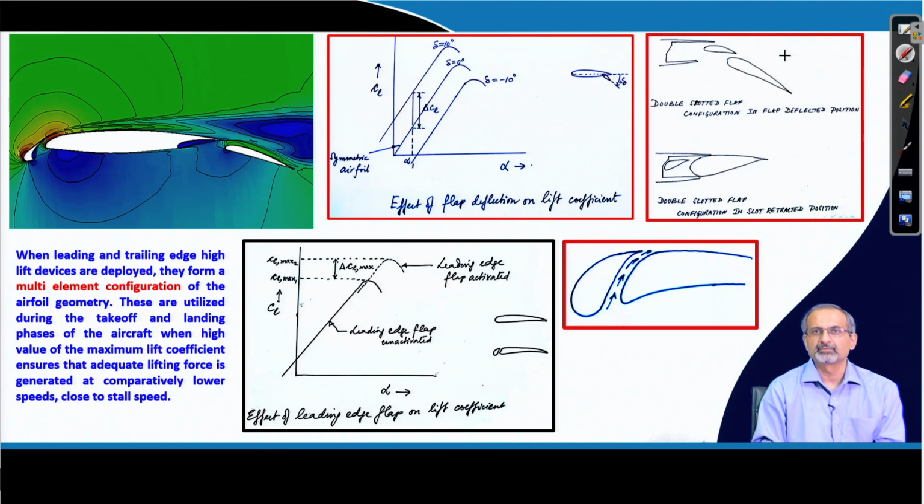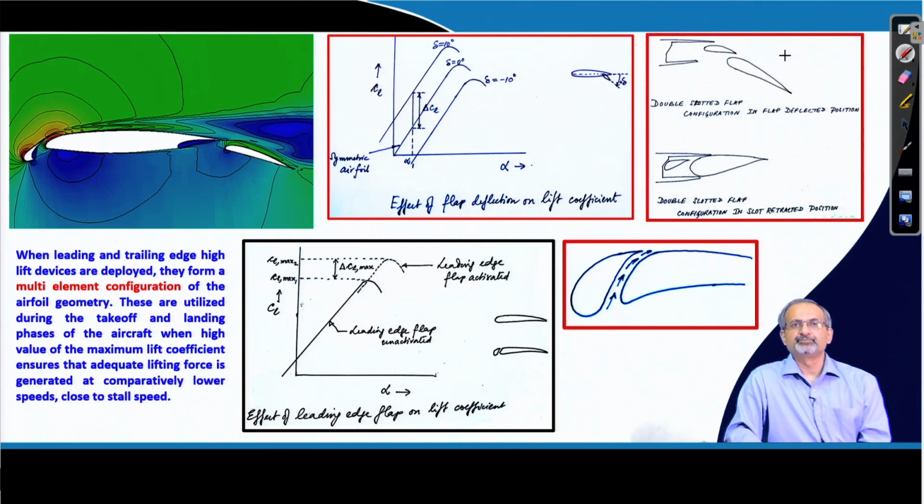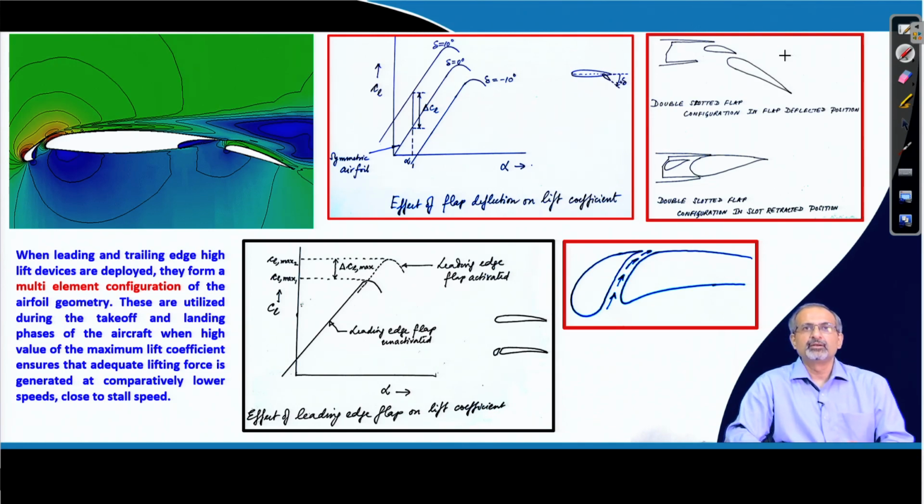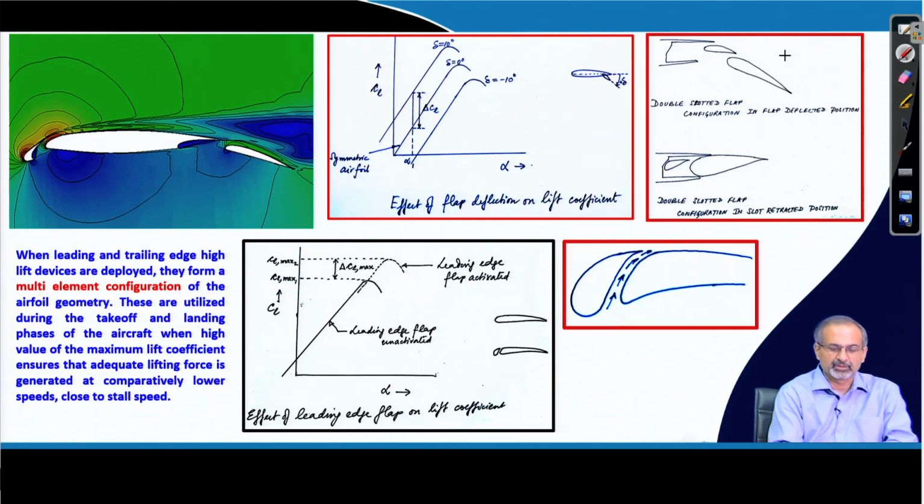That will not serve the purpose, because in practical vehicles, if you come across such a crisis, the vehicle will probably lose altitude dramatically, it may even crash and things like that. So, what is the way out? We have discussed it. The way out is to deploy high lift devices.